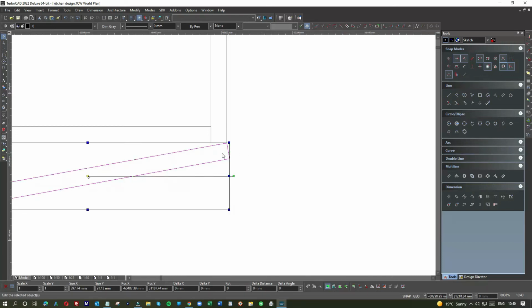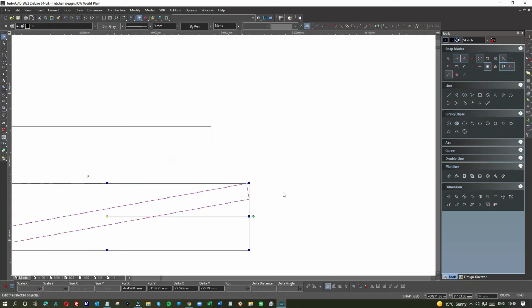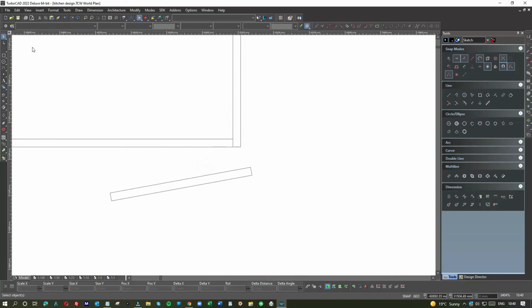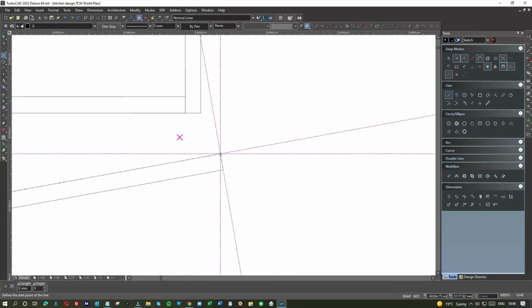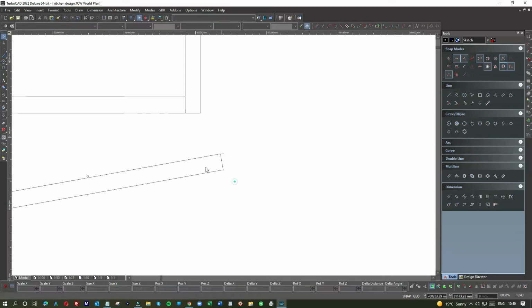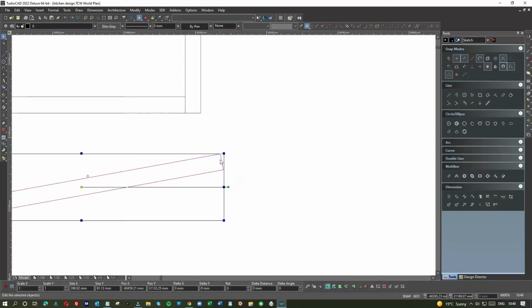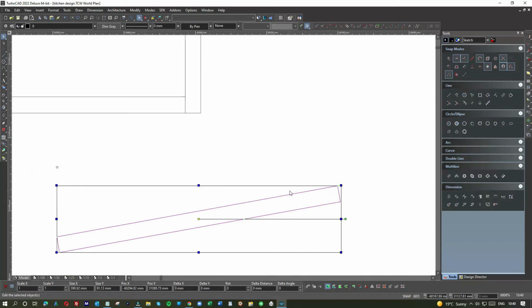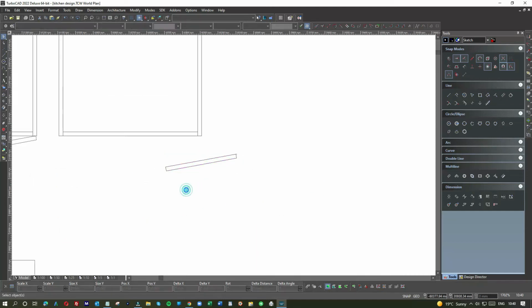So the doors always sit in 5 mil. From a design point of view, what did I do just there? This is a cheat, of course: I do a tab 5, so I've got a little projection of 5. This is basically for joining up. It's an easy way of doing it. In fact, I'm going to make a copy of that before I join it.